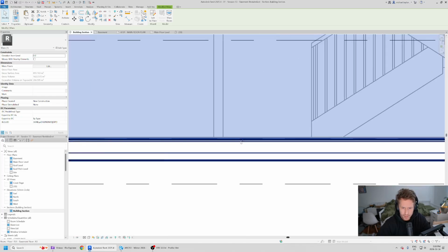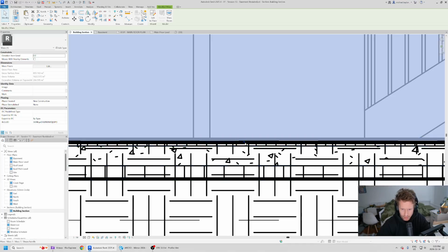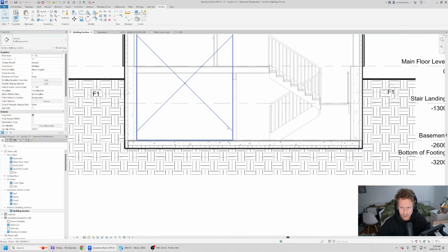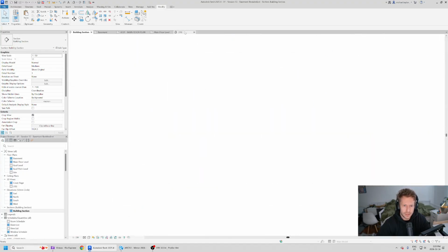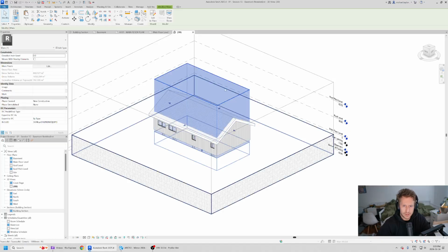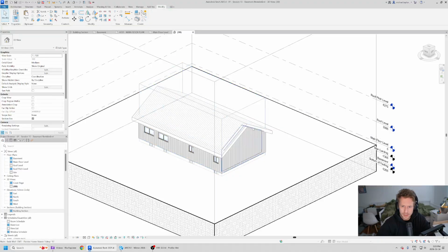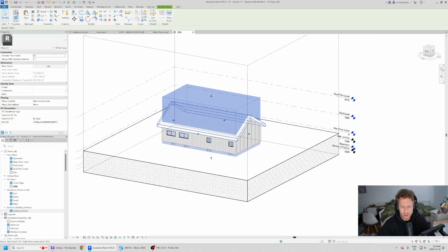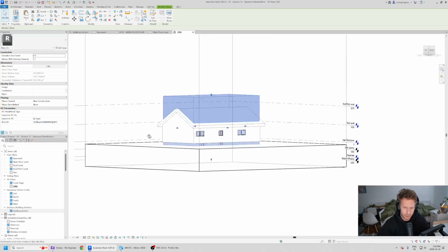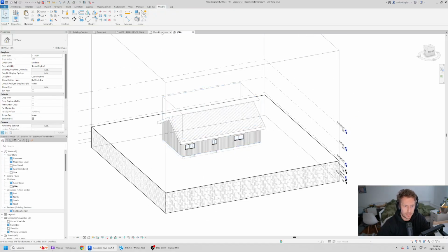We are missing the basement slab, so I'm going to drag this very small triangle here. I can drag this down, and now we're cutting through the whole building. Looking good. Let's go to 3D here. Everything's looking all right. So in fact, just drag that up. And this is really what's making up our cutting plane, or a cutting volume, for lack of a better word, of our Toposolid. So that should help us get a little bit further.